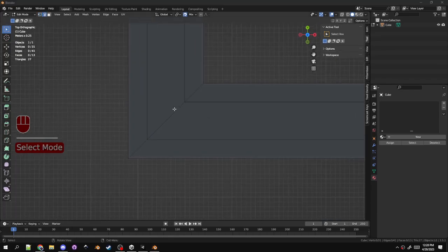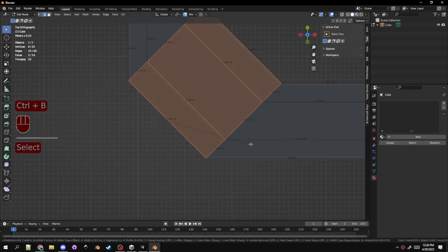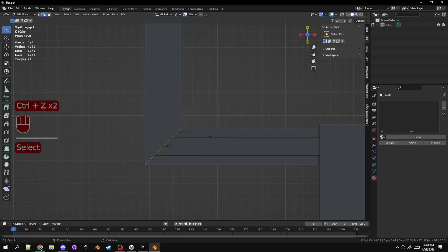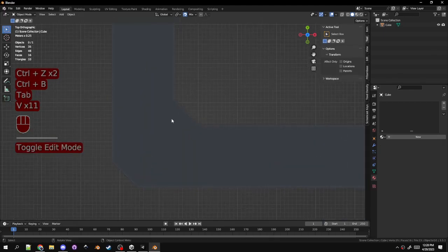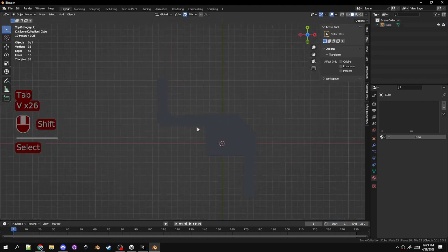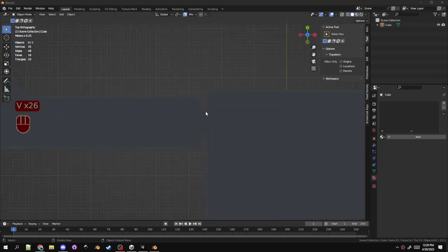We can make this hallway more interesting if we select and then press Control B. Now we have a bevel bit here. Pretty cool. See, just like that. You have a corner bit now. And as long as you keep adding doorways and stuff, you want to keep segments connected by a 0.25 thick gap and a 2 wide gap or a 1 wide gap here so the doors snap.